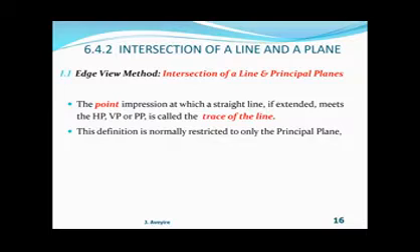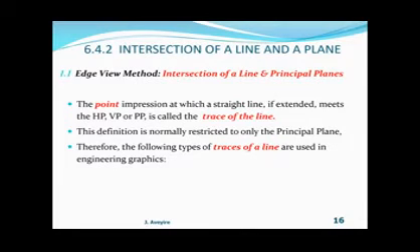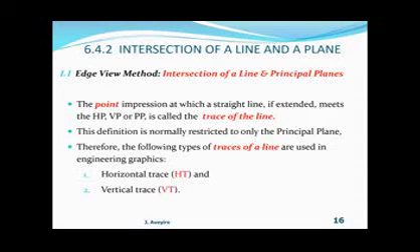This definition is normally restricted to only the principal planes, and therefore the following traces of lines are used in engineering graphics: 1. The horizontal trace, HT, of a line, and 2. the vertical trace of a line, VT.